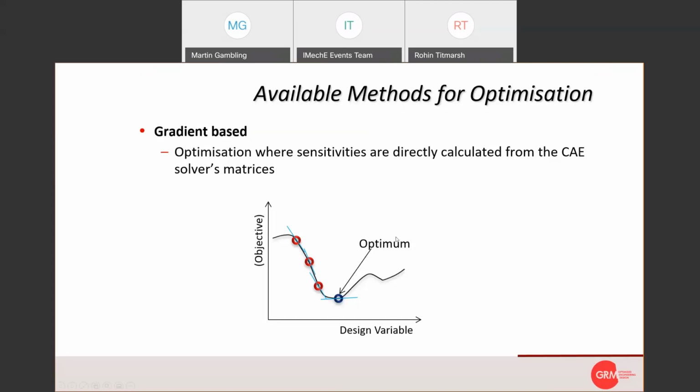So what we do, I did have a slide of this once that explained it, is we use a design of experiments Latin hypercube to start multiple gradient-based solutions. We do it all in Solve, it's all managed inside the code. We'll start at this position, we'll start at this position, and typically we'll start around about 10 different positions, and internally it will solve the gradient solution 10 times, and it will monitor the best solution and say, there we go, that's the best one. It doesn't guarantee you're at the global, but it certainly gives a very much stronger chance of doing so.